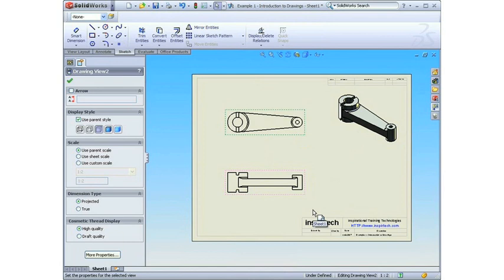The theoretical things that you don't actually see. The other aspect to a drawing file is the sheet format. And the sheet format is this outlining border that's not part of my components. It's the information captured that displays the vendor, the part name, the date it was created, the drawing by. All that information that you would generally think of as a template is actually called the sheet format.